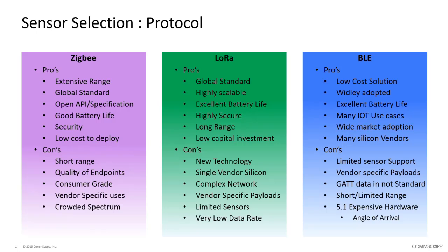One of the bigger issues is that the payload itself tends to be more proprietary. So the thing with BLE is that there are different ways that you can connect to it. There are beacons that are transmitting, and again you can view our video on BLE specifically. There are beacons with payloads that are defined, iBeacon, Eddystone, URL, different types of beacons, payloads that are out there. But the actual formatting of the data in there can be proprietary and specifically coded.